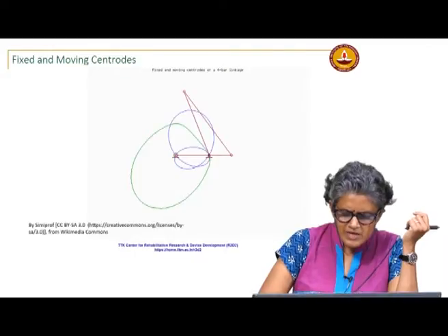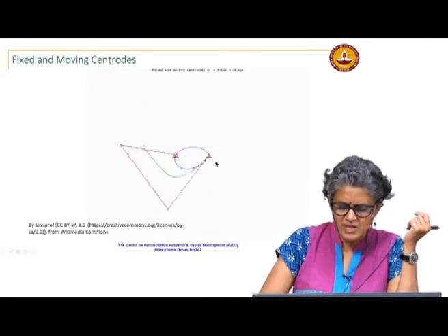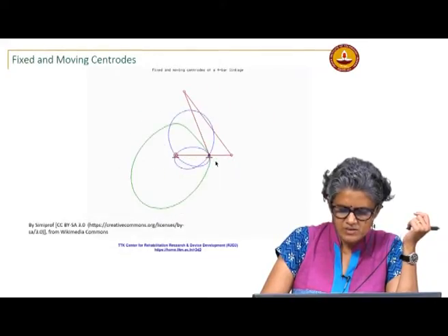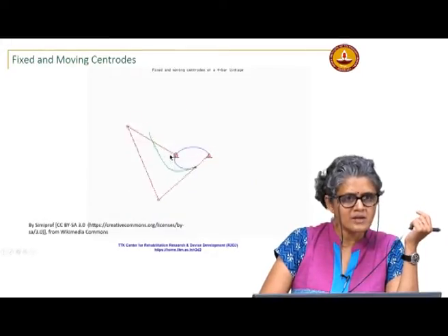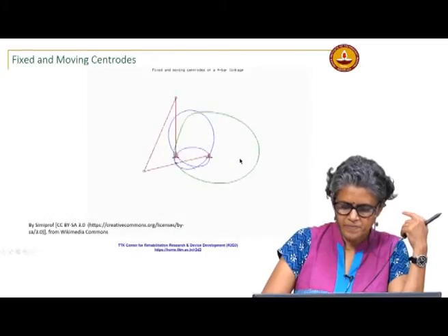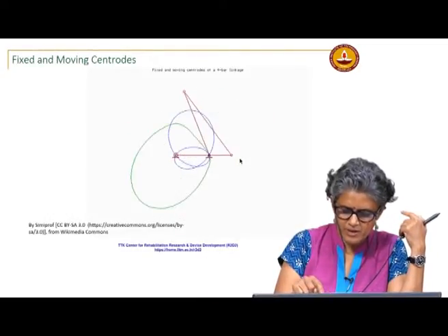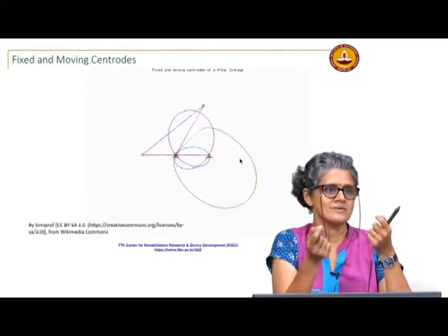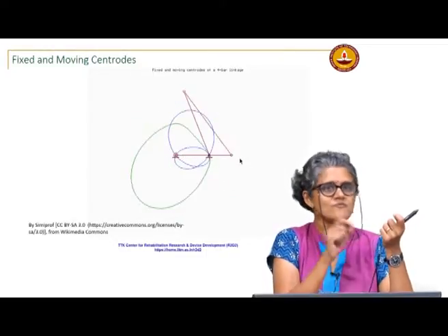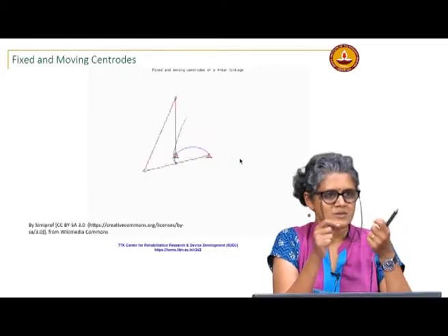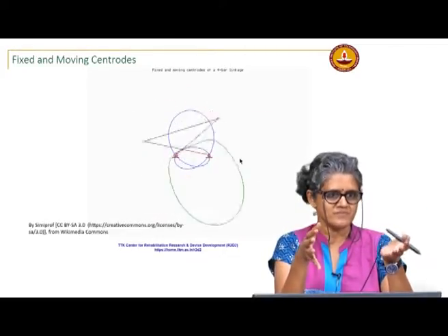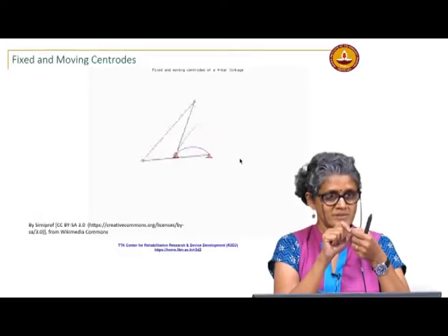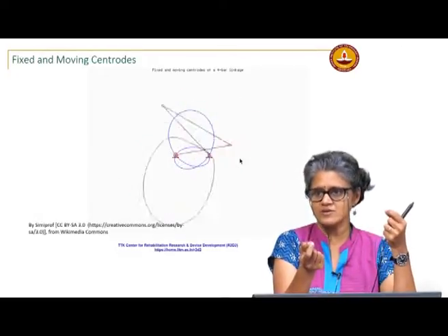Your curve is intersecting here, so that means it is contacting it, but at two different instances. So, it is possible. Then see, if you look at this one here, you have a coupler point on the move. The question is whether the same point will contact the fixed centroid multiple times, which may not happen, because you could have multiple points on the centroid which will generate cusps, but is the same point going to contact the fixed centroid?